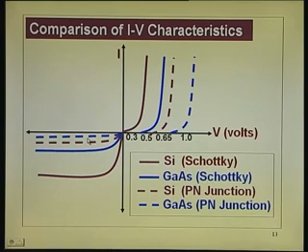Also, you see the currents, starting from this dotted line, higher voltage, lower J naught. This is the curve from here to here, and this one is the silicon junction; that dotted line is the second dotted line. So, here you move from this side to this side, and here you move from below like that. Smaller forward voltage, larger leakage, and if the leakage becomes largest, that is the ohmic contact. So, if this curve keeps on shifting towards the left side, this keeps moving down and you will have ohmic contact, close to the ohmic contact.